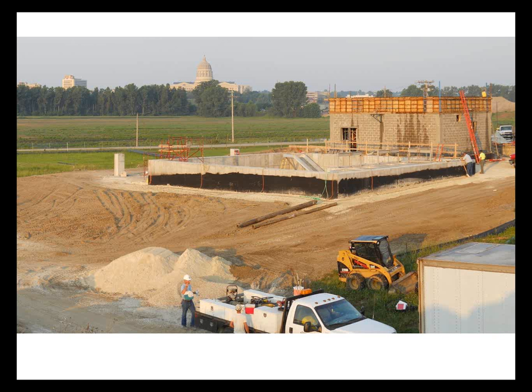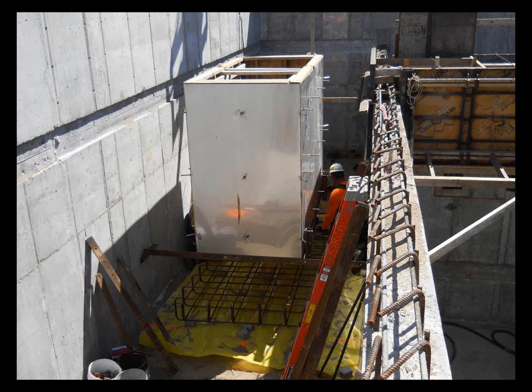Once the leak test was passed, piping was laid, we backfilled around the basic structure and started on the control building. This brown block building you see here is where the controls will be for the UV system. This is the dip tank that I mentioned earlier being installed. The rebar tied around it. This tank is filled with a citric acid solution, and we pull our modules out and dump them in the citric acid solution twice a year in order to clean all the deposits and scale off the quartz sleeves.